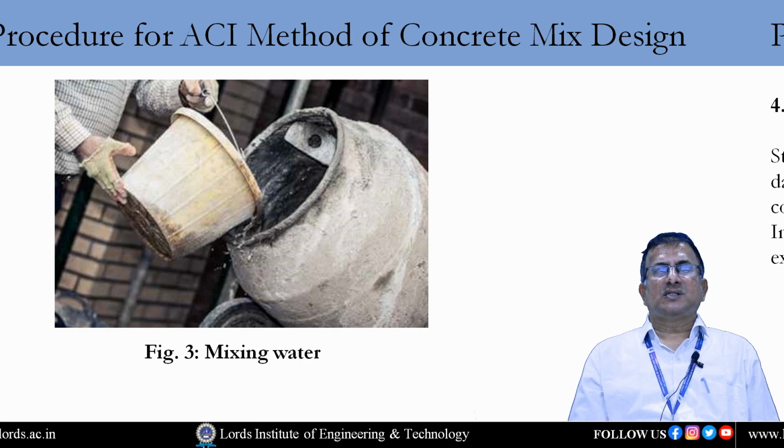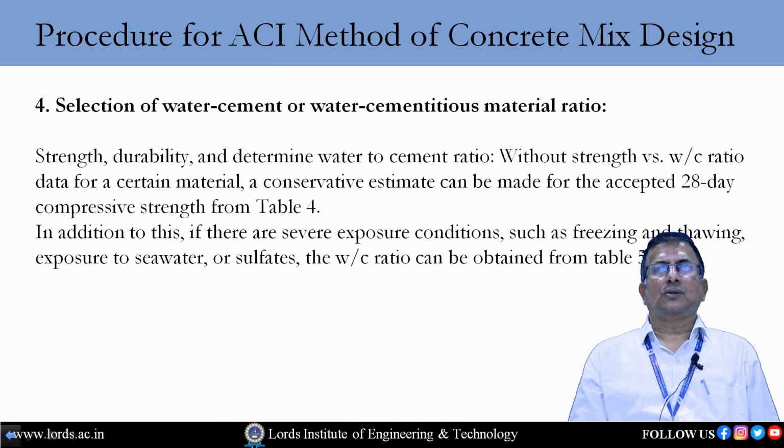Now come to selection of the water cement ratio. Here, the selection of the water cement ratio is shown in Table 4, purely based on the compressive strength of the concrete, and also for different exposure conditions, freezing and thawing, and also for seawater exposure, we can select the water cement ratio from Table 5.